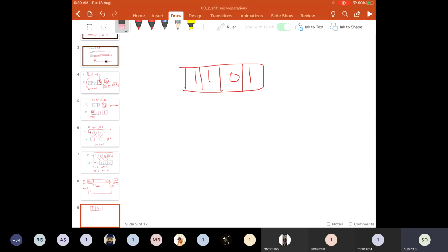I'm getting confused by it. In logical shift left, we will be just discarding this bit, the rest will be the same and a 0 will be inserted here. We are moving left one position.